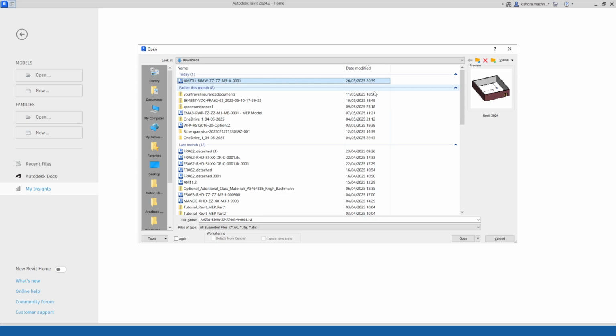I think I've shared the Revit files within the Revit materials. Those are like 2016. Most of you, what you have done, you just download it and then double click on it, isn't it? No, you should not do it. This is a tip I can give you. Even if you work on any live projects, even if you download it, don't ever try to open the model by double clicking on it. This is the first tip which you should use and practice when working on Revit files.